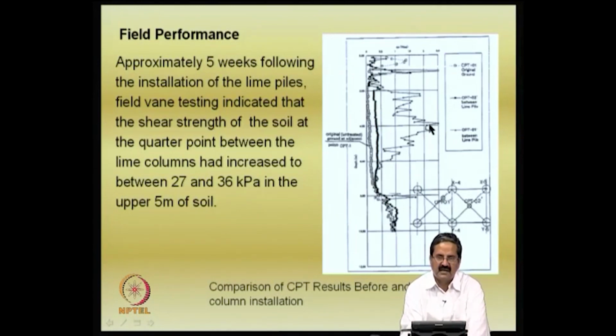If the test does not allow you to do anything, then it is very difficult, because how are you sure about the quality of the work done, which is something very very important. And if I cannot give you the strength improvement in calculations, and also show you later with CPT or SPT or any other test that the strength improvement is achieved, then, say for example it is 15 kPa, now it is 36 kPa, which is quite good, right.